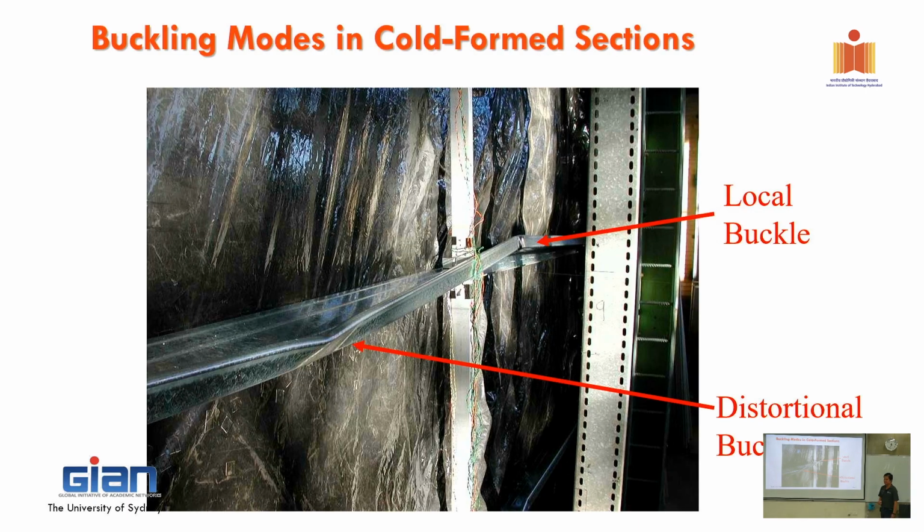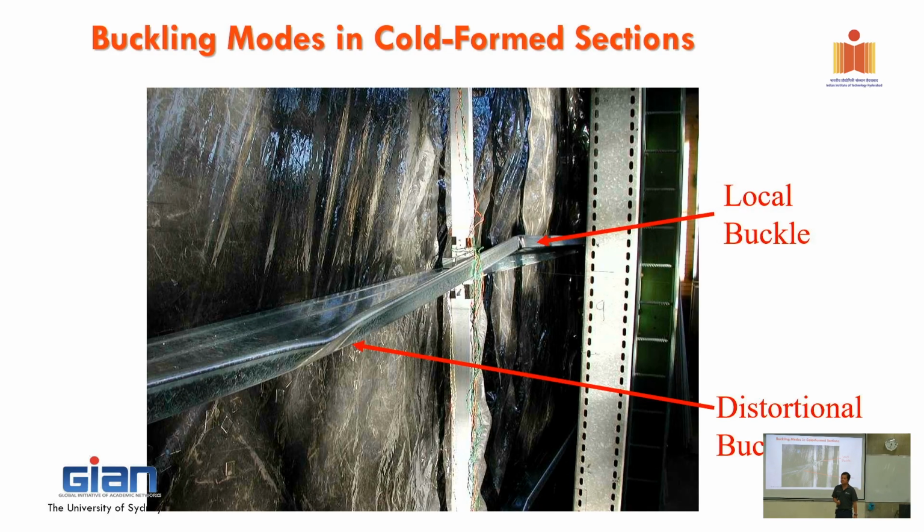Okay. Good. Sometimes yes, a mix of two modes. Sometimes, remember, it may be a mix of any two modes. Oh, that's a very good point. So that's what we call interaction. So now in here, probably this figure tells you that it buckles maybe in a combination between local buckling a little bit and flexural torsional buckling. So in the DSM equation, there's a part that takes into account the interaction. So that's a very good point.